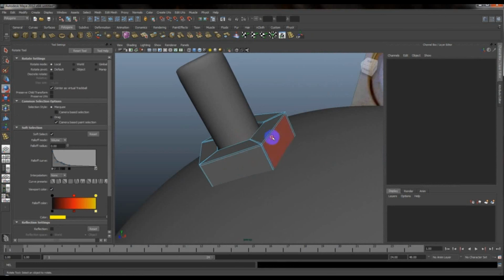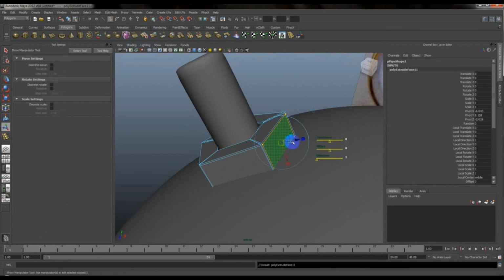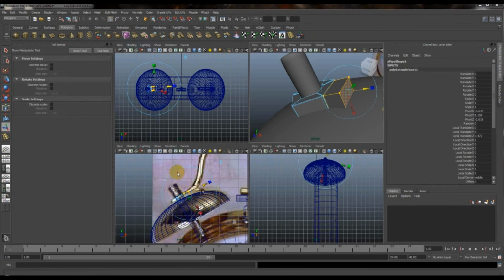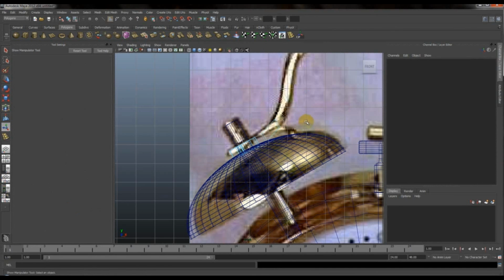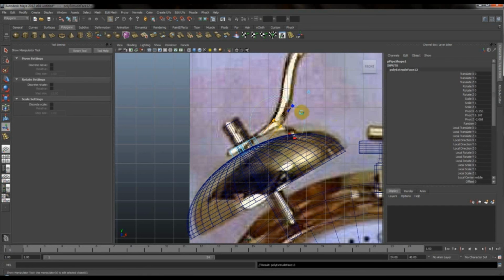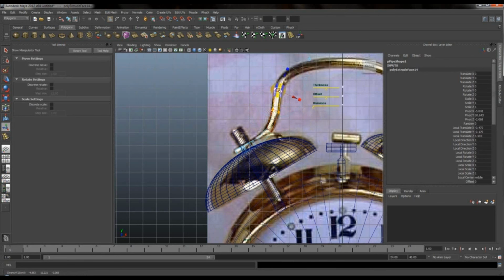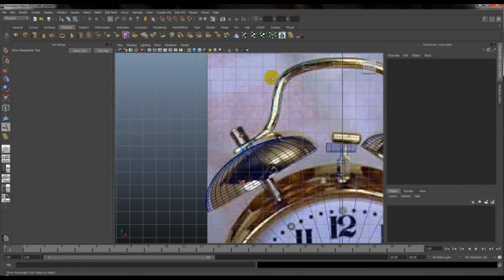Select the faces again. Maybe extrude these two faces. As you can see, I'm extruding this face now until I get the result to make the holder of this one. I'll make another extrude by clicking the G letter and make it a little bit higher, rotate it until I get the shape of the holder. Another extrude again, another one rotating it till I get to the half, which is in the middle. That's enough for me. Yeah, till here.